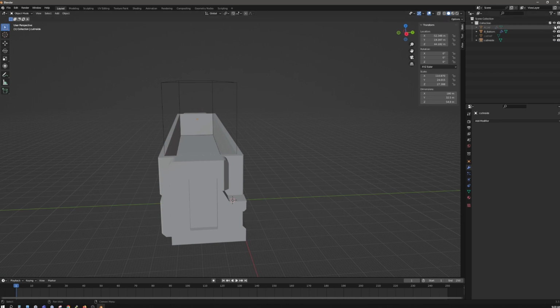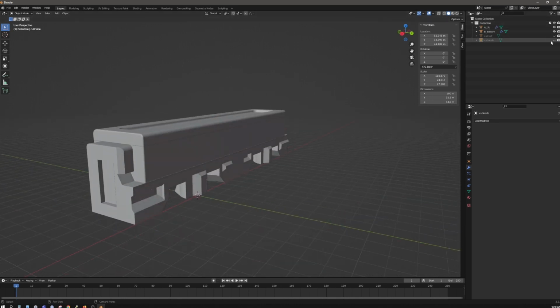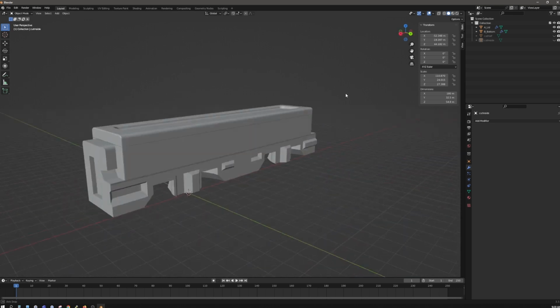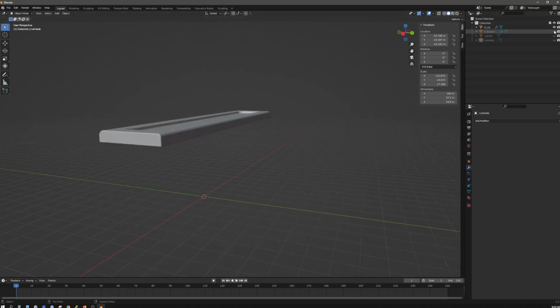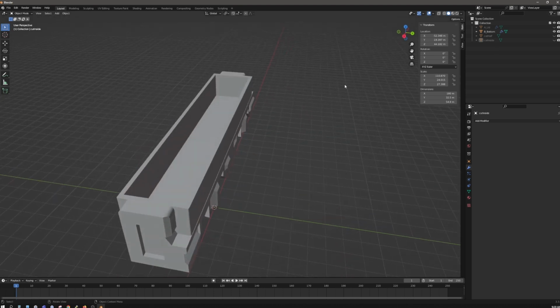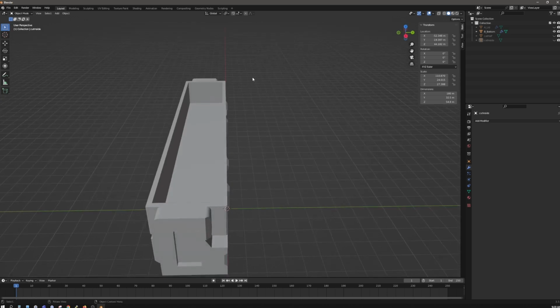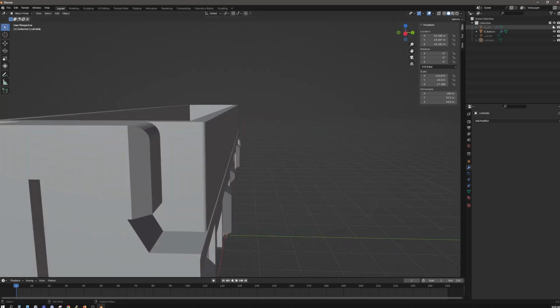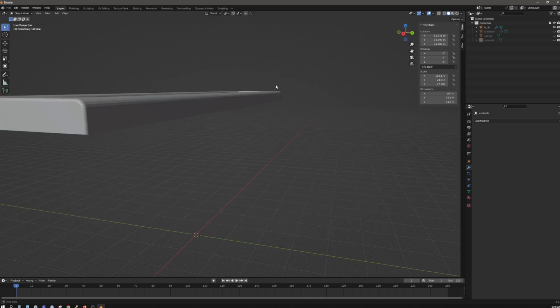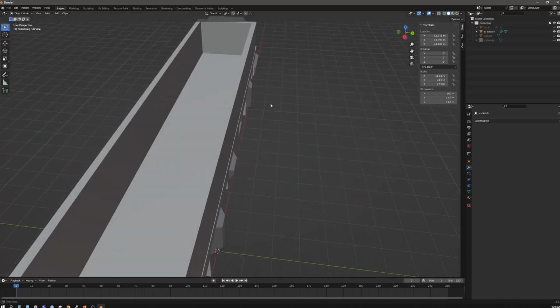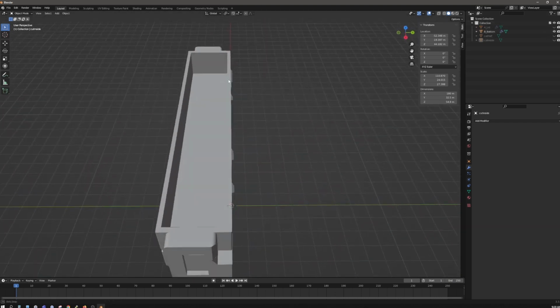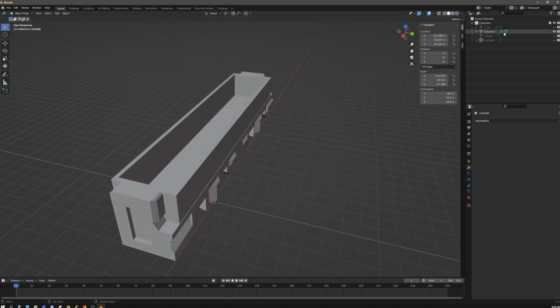We're done, right? Let's put our lid on and we're done, right? Yeah? No, we're not, because we need a way for this lid to stay on there, because if we put it on right now as it stands, it'll just slide off. So let's put a lip on here to cut a groove in the upper part of this lip so it has something to latch onto. All right, this is where basic industrial design comes in. All right, so what we need is to take this wall, extend it up just a little to create a lip, just the wall, not the thickness of the wall.